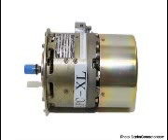In position B of Figure 9.7, the flux is being cut at a maximum rate and the induced EMF is maximum. At this time, the black brush is contacting the black segment and the white brush is contacting the white segment. The deflection of the meter is toward the right, indicating the polarity of the output voltage. At position C of Figure 9.7, the loop has completed 180 degrees of rotation. Again, no flux lines are being cut and the output voltage is 0.